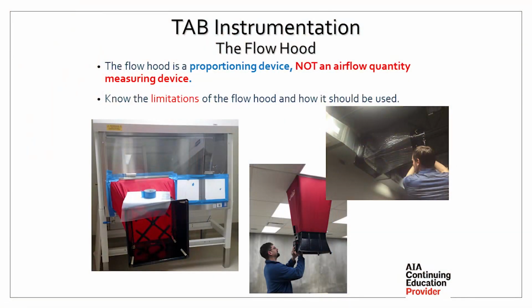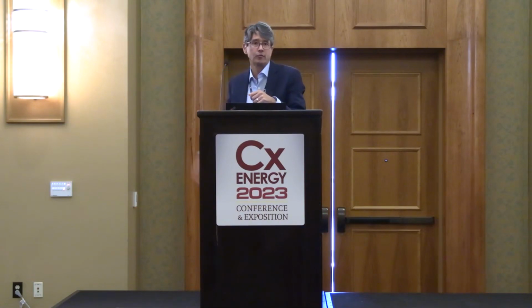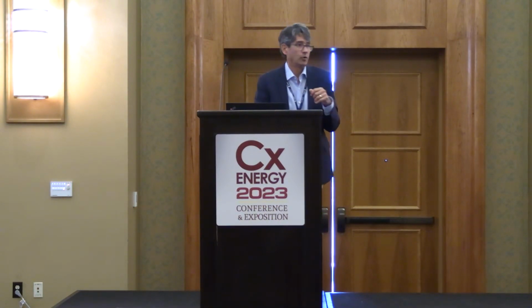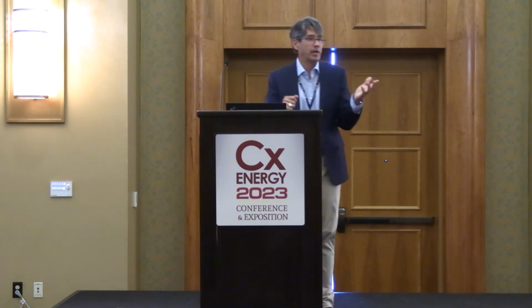Second biggest thing I can say about airflow measurement that we'll take away today is the flow hood. It's not an airflow quantity measuring device. It's a proportioning device. So when you look at that and say, how am I going to use it? I get pushback on the far left one with the flow hood. There are some fume hood manufacturers that say this is how you're going to set up my fume hood.